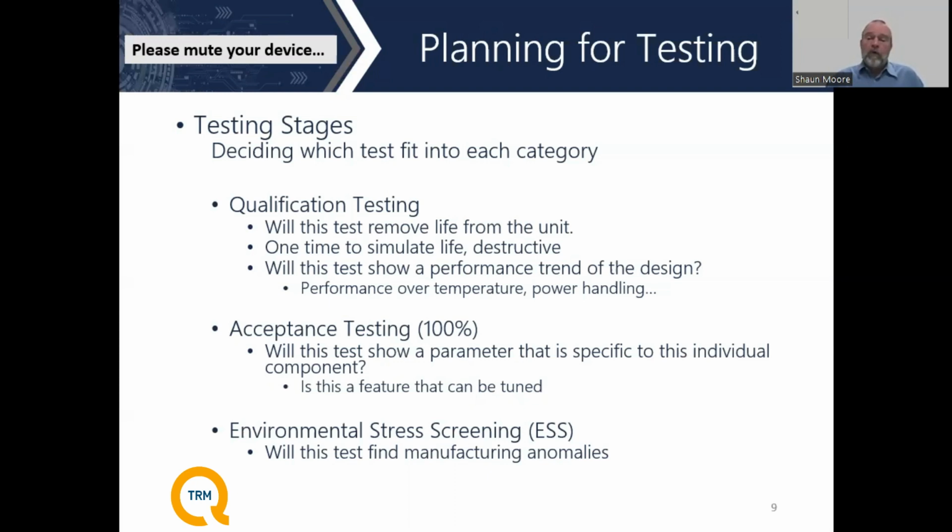We will do vibration and thermal cycling to make sure that the part will survive and be compliant over all of its operating environments. Very often we will do TVAC testing and other sorts of testing to make sure that we don't have any kind of corona events. There's leak testing. There's all kinds of things we will go through to make sure that the part is indeed meeting all of its requirements.